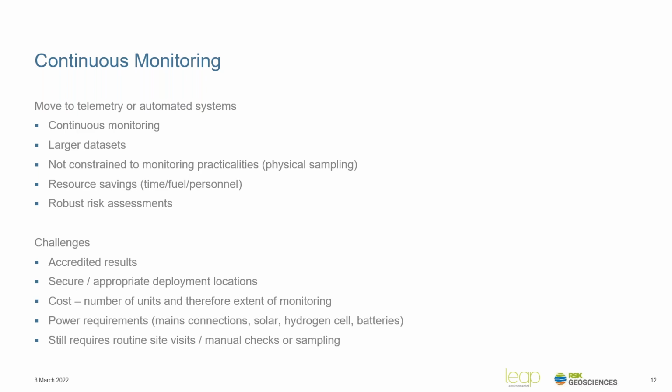And what we used was a couple of water quality probes with a telemetry system, and it helped us pick out which of the tributaries the bulk of the contamination was coming from, and informed where we went with, refined our monitoring visits thereafter. And also confirmed and validated that, yes, there is a spike in the morning and again at lunchtime and again in the evenings. So sometimes we're omitting that from our monitoring.